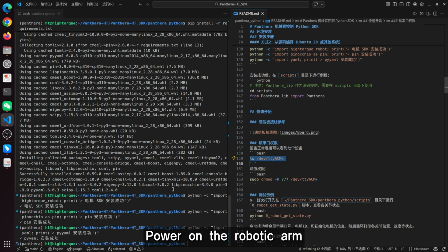For state readout, you can use these get methods to retrieve the position, velocity, and torque state of each joint, as well as various states of the gripper. On the control side, there's joint position velocity control with maximum torque, joint velocity control, Cartesian space motion control, and many more.